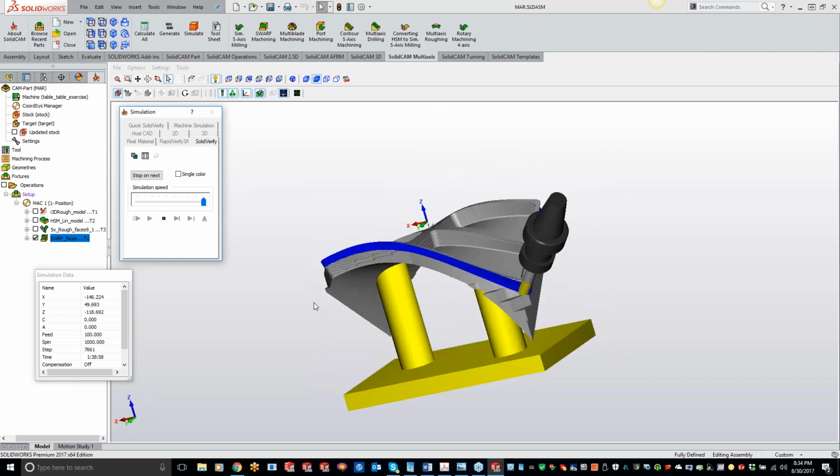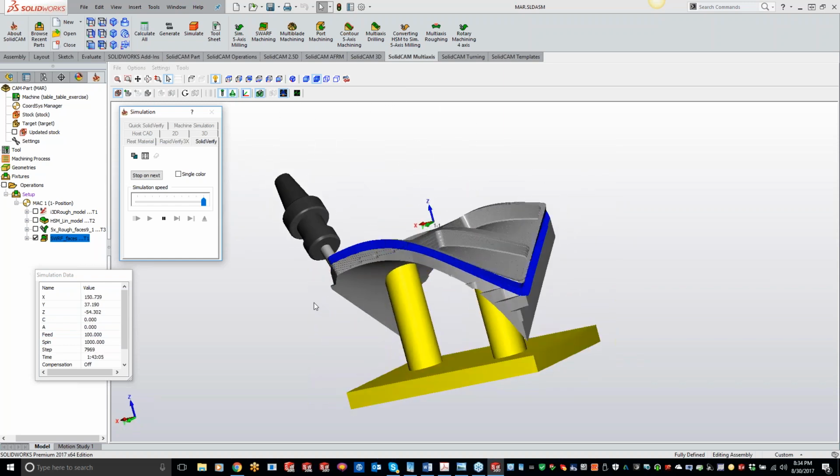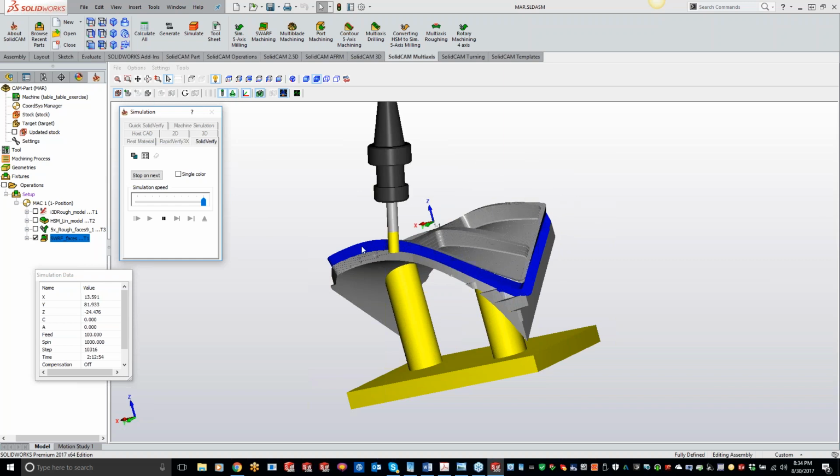Now, one thing as I'm getting more familiar with the Swarf here is that there's the functionality inside of simultaneous 5-axis where you can do a spiraling down. This one does one pass around and then it stops, comes out, comes back in and goes down and makes its pass around. I'm going to see if I can talk with development and see if we can get that spiral functionality transferred over onto this portion of it.